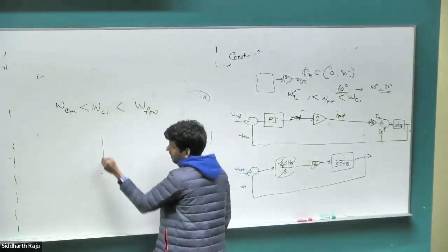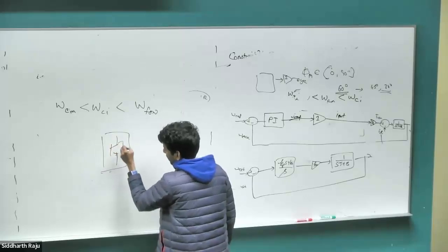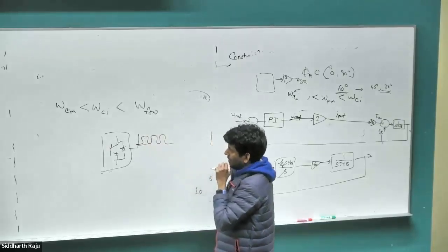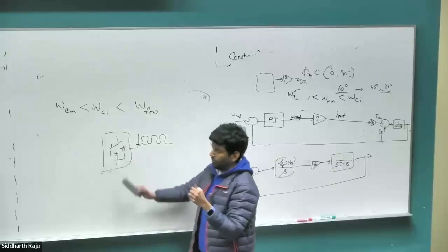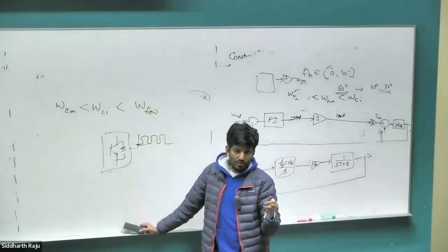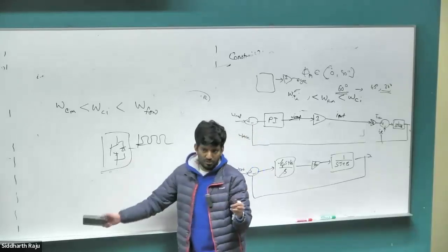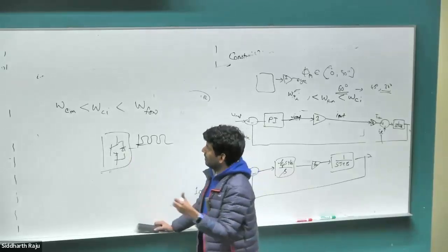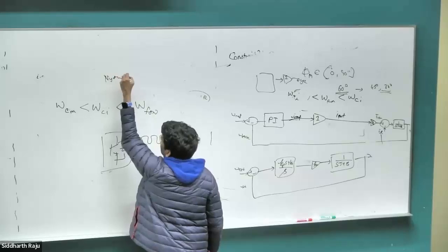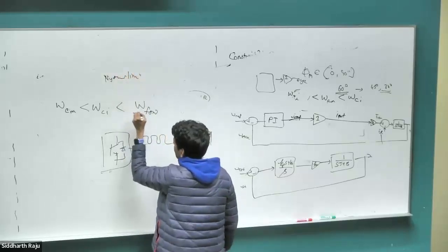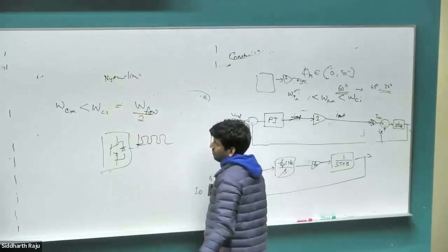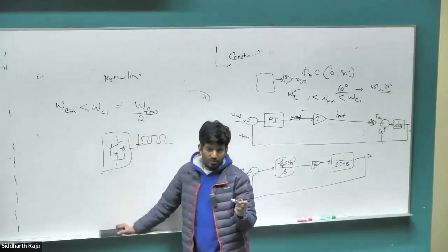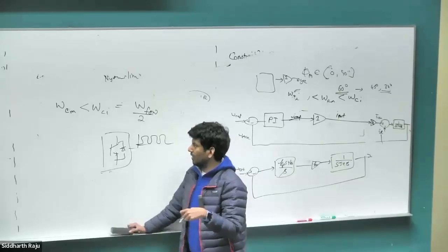FSW. So if you have an inverter, which we looked at in the third lecture, and this is creating some switching output voltages, you cannot expect the current to be created faster than what the inverter can switch and create the current in. At the end of the day, when you resolve it into Fourier components, it has to be a multiple of the switching frequency terms. You cannot create some other random frequency which is much higher than this. So that would be the Nyquist limit, which is the very upper bound, saying that at the maximum it can be half of the switching frequency. So if you're switching at 10 kilohertz, your current controller bandwidth cannot be greater than 5 kilohertz. Afterwards, you'll get aliasing and the control system could start to act quite crazy.